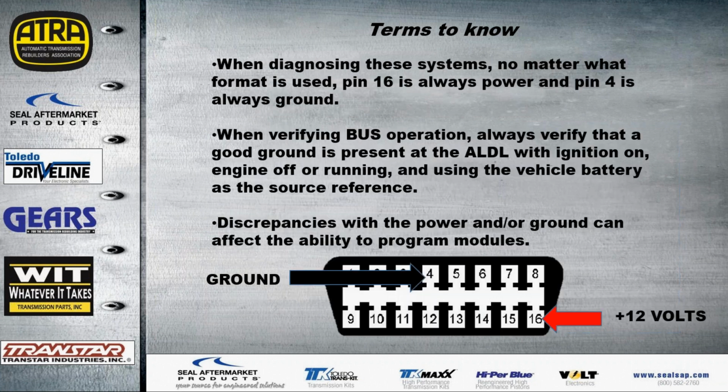When diagnosing these systems, no matter what format is used, pin 16 is always going to be 12 volts positive, and pin 4 is going to be our chassis ground. We always want to verify for a good chassis ground on all occasions. We want to do a voltage drop on this with a key-on engine off or key-on engine running. And we want to make sure that we have 0.1 volts or less.